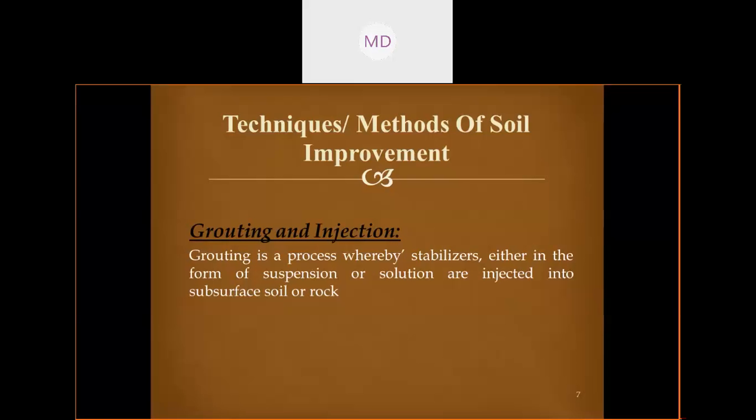If there are lots of voids, what will happen? If we apply some load, it will settle. So the chemicals which are injected fill up the voids, and they reduce the amount of settlement, or remove the settlement process. Then it strengthens adjacent foundations to protect them against damage. It protects the foundation from getting damaged, because if settlement occurs, first of all the foundation will have to suffer.